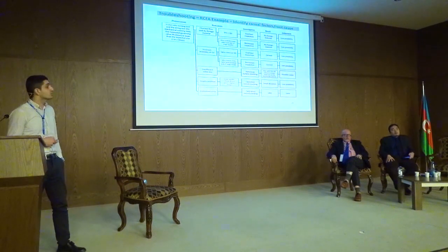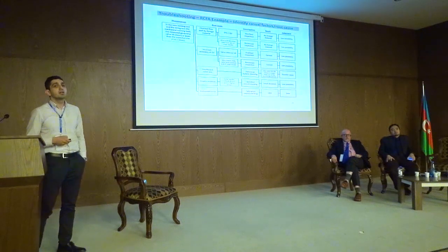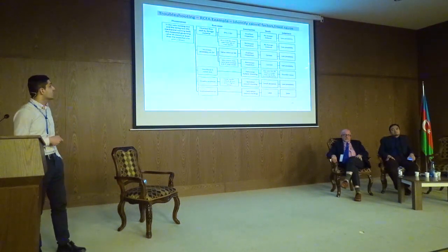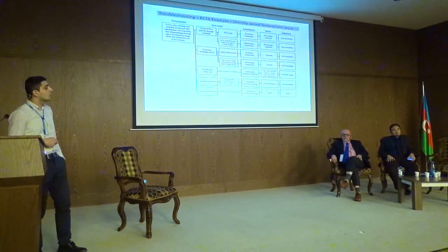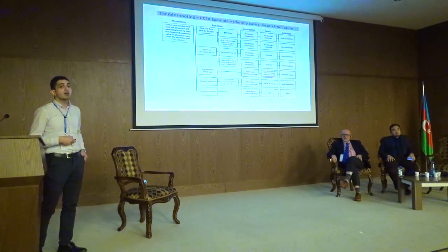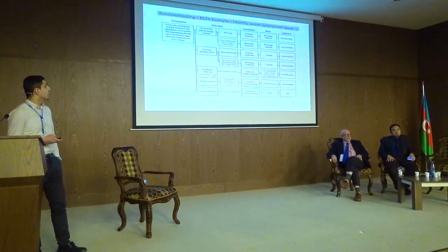The valve size was 22 millimeters, whereas the valve size in the steam turbines in other plants was 28 millimeters. So this was identified as a very likely root cause, and the solution was provided.